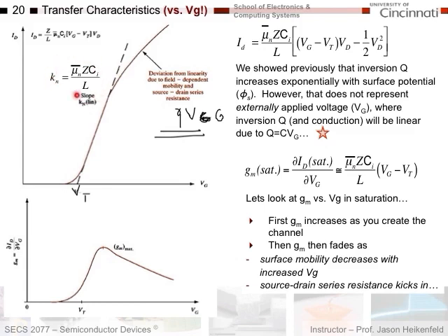You can see I get that same transconductance parameter I had in the equations before. It's the slope of this line, and lo and behold, VG turning into current. There's the slope, transconductance parameter. It should all make sense.